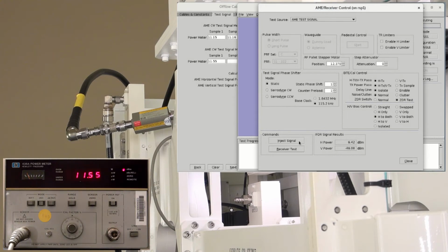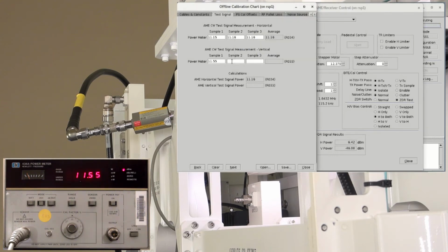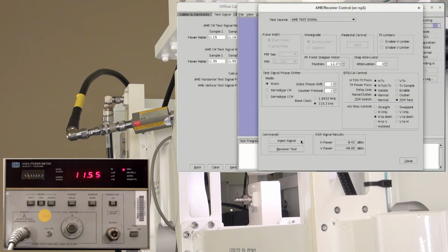If the expected test result is not met, replace the QN male adapter on the cable. If that does not resolve the issue, perform Fault Note 82. If Fault Note 82 passes and the expected test result is still not met, replace cable 2W574.